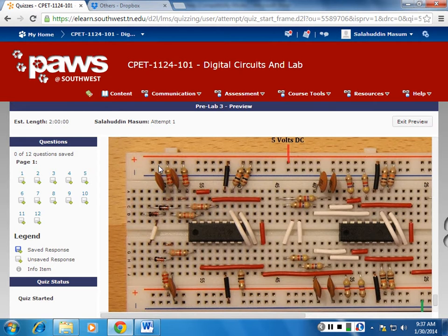Because you are trying to operate the IC, it's just digital equipment, right? So you have to give some voltage there. There will be a pin. For most of the ICs, the pin is 14. Not all, so don't trust this. Just check the layout. It might be a different pin. For most ICs it is pin 14, so pin 14 is mostly connected to voltage 5. In most of the cases. Not here, because it's a different IC.